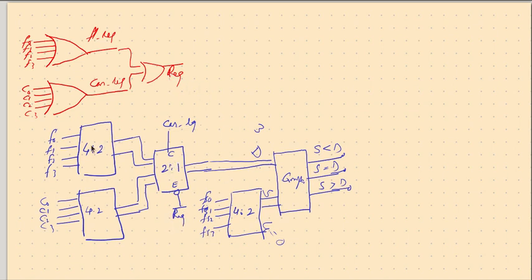And is the request coming from the floor or from in the car? So we are giving the in-car request signal as the selection line, and when this is 0, then floor inputs are connected to the output.